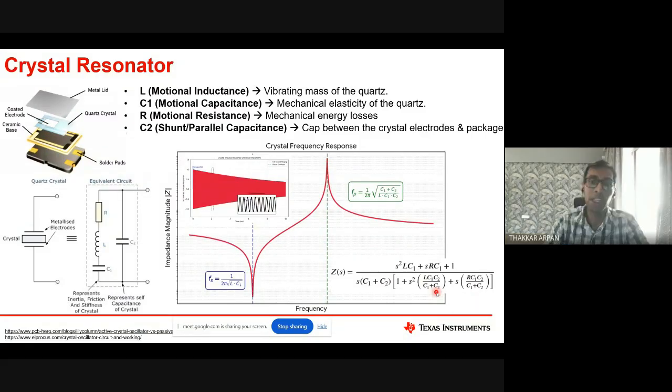No, no. It is because we are not operating at this frequency. In any oscillator, the first thing you have to understand is that it works on the Barkhausen criterion. What is that criterion? Wherever the magnitude becomes 1 and the phase becomes 360, in that condition only it will oscillate.